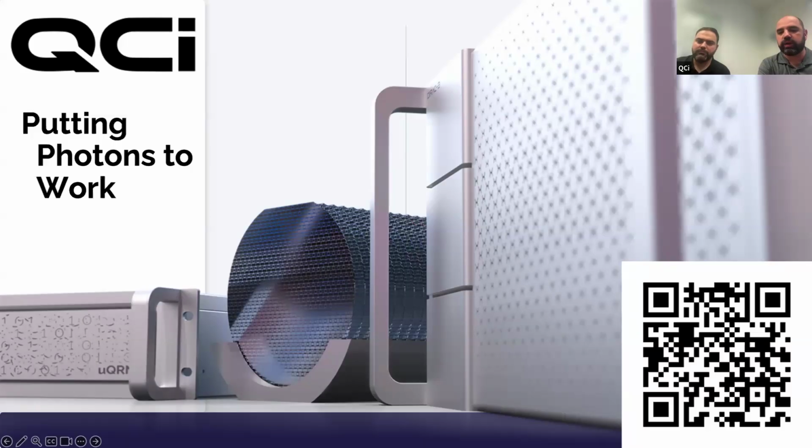If you're talking about a single modulator in particular, 30 is doable, but the question then becomes, how good is your fabrication? If there's a little bit of inconsistency in the beam splitter that can be introduced during etching, that's where you will see degradation in the extinction ratio. So 23, 25 is what we typically see, and as we improve the process over the next few months, our goal is to get closer to 30, but beyond that, you would have to cascade the modulators to achieve that type of performance.